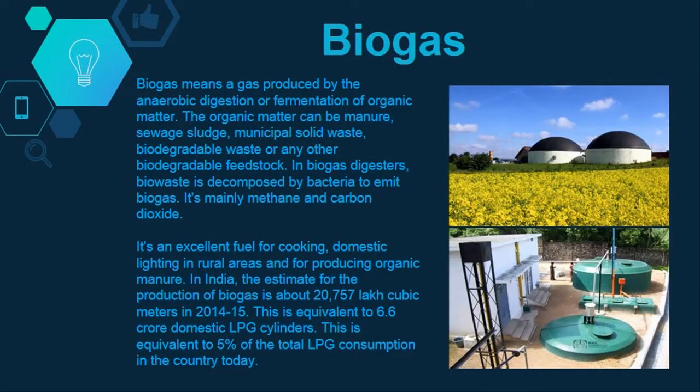Biogas. Biogas means a gas produced by the anaerobic digestion or fermentation of organic matter. The organic matter can be manure, sewage sludge, municipal solid waste, biodegradable waste, or any other biodegradable feedstock. In biogas digesters, bio-waste is decomposed by bacteria to emit biogas. It's mainly methane and carbon dioxide. It's an excellent fuel for cooking, domestic lighting in rural areas, and for producing organic manure.